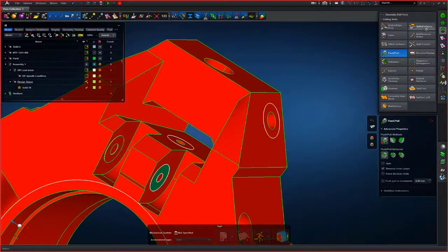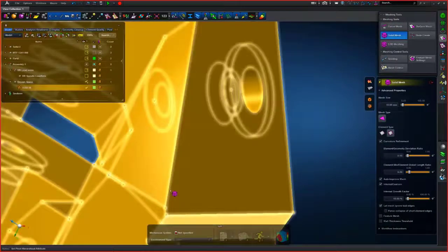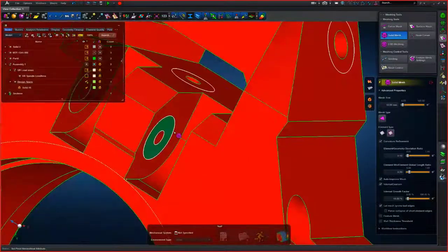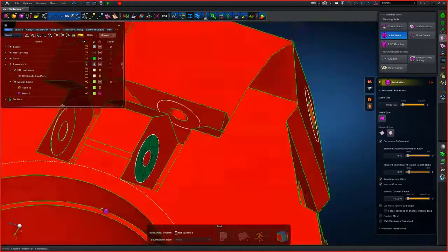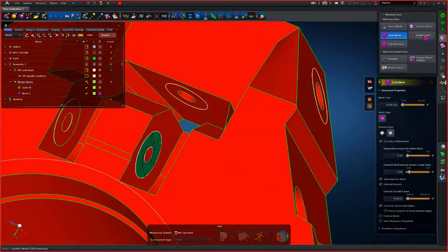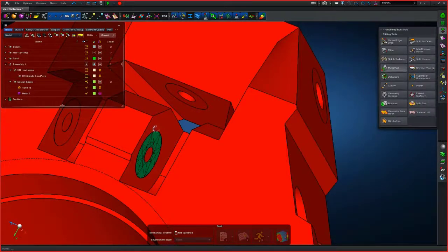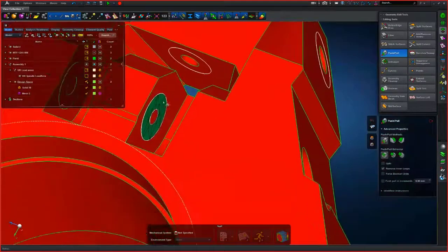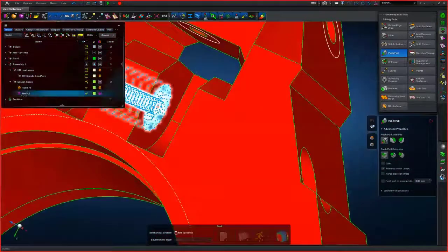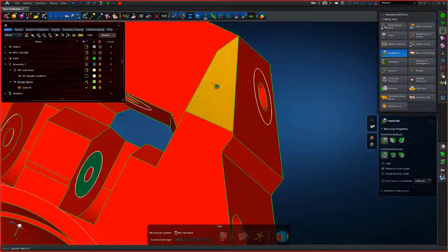The only workaround that I have for you in that case is, let's say, for instance, I only had this body meshed, and I want to make a CAD modification, but I don't want the mesh to update immediately. The only workaround that I have is to delete the mesh. So that would be the easiest way.